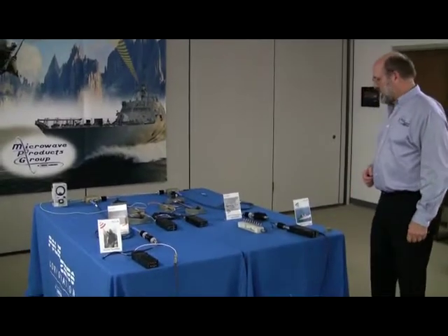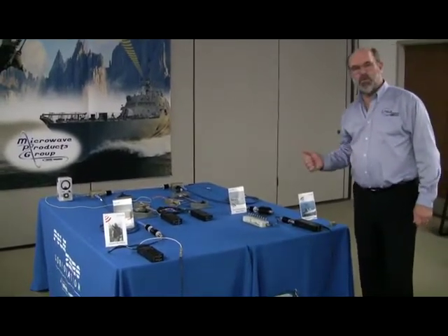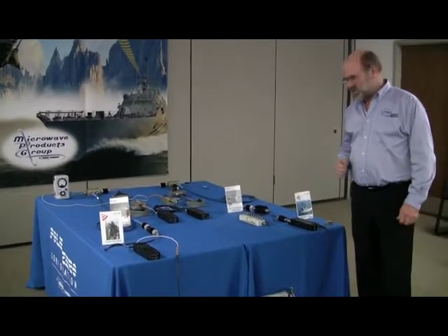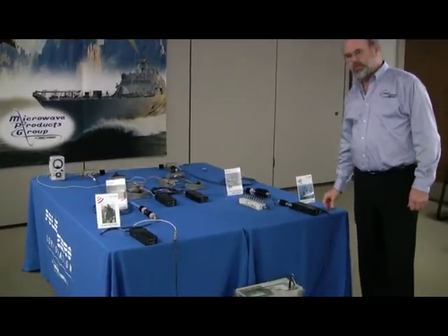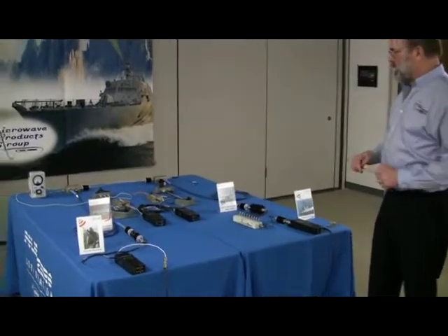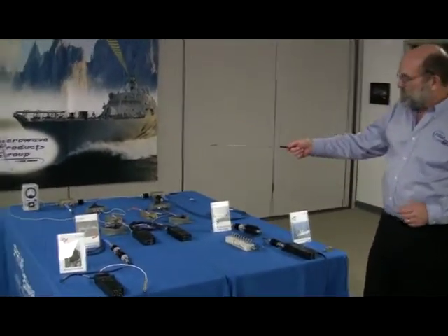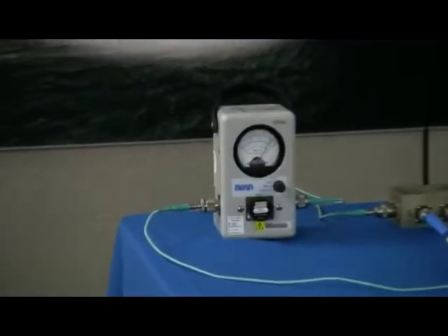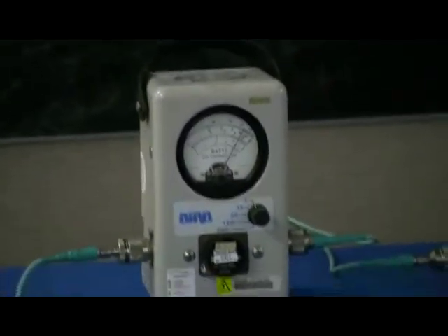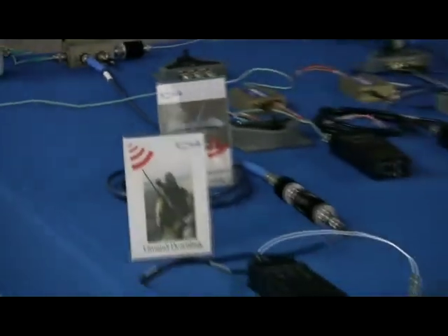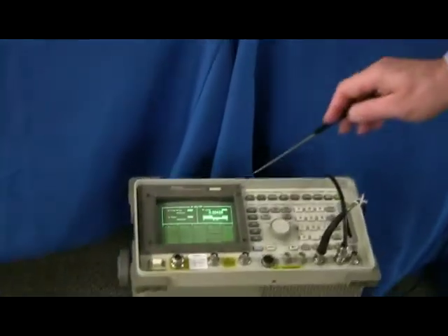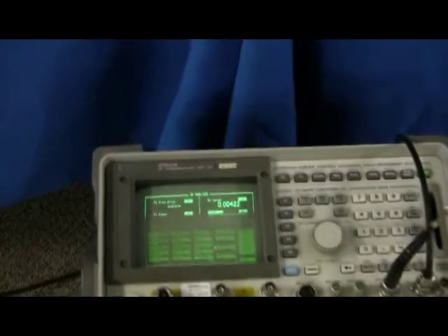All right, so let's look at the case where we're bypassing both Cosite mitigation units, but we have the 40 dB coupling between the two antennas. We're going to key the system, and we'll note at the power meter that we have approximately 5 watts of output power, which is what we would expect. That's downlink output power. The audio is coming into the communications analyzer, and if we look at the SINAD reading on the communications analyzer, we have no attenuation on the uplink transmitter. We see that we have a SINAD value in the high 20s.